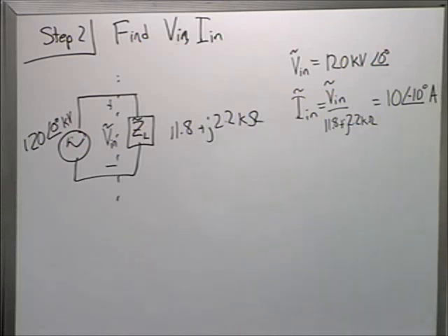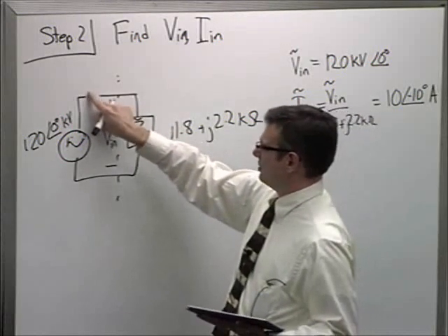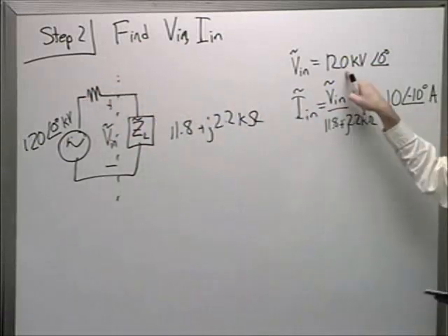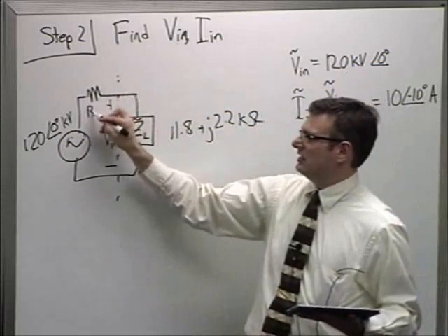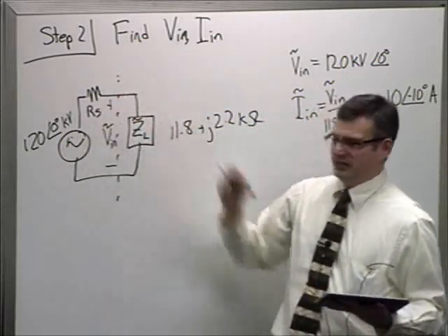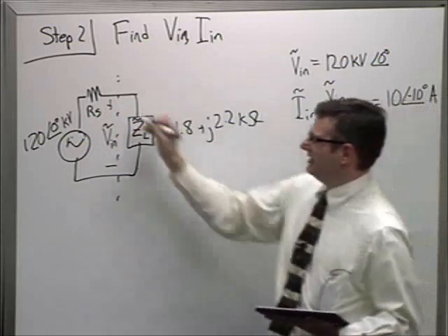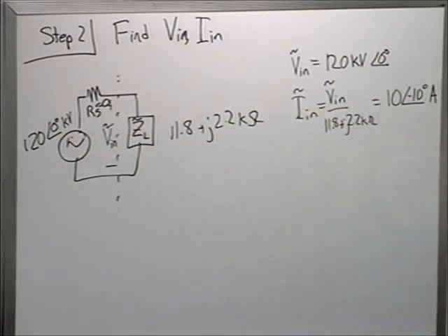Yeah? So when you have a source resistor, would you be able to change it? Yeah. If I were to give you a problem with the source resistance, this would be a voltage divider across whatever resistance value I gave you here, and whatever load impedance there, ZL over. I should have thrown one in because it's not that hard. But instead I said this was 0. No big deal.